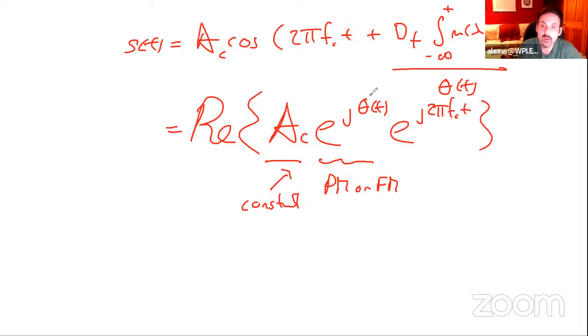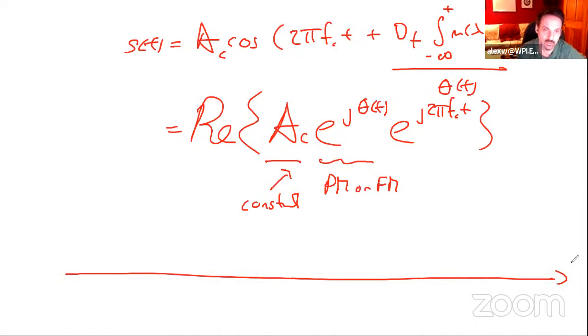And there we go. What would happen is this integral expression is really nice because it goes from minus infinity, and it allows for a smooth transition of that phase term, right? Let's say a binary 0 had a faster frequency than a binary 1 every Ts seconds.